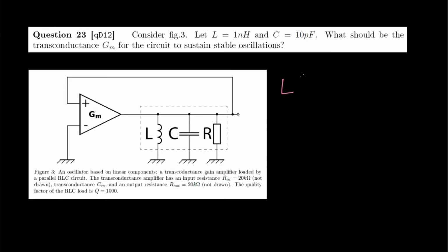So, to write that down mathematically, the Barkhausen criterion tells us that the open loop gain has to be 1 with a phase shift of 0. Since the phase shift of the open loop gain has to be 0, we know at least that the frequency of oscillation can be found when the impedance of this RLC circuit has no imaginary component. In other words, the impedance of this capacitor and this inductor completely counteract each other and can therefore be cancelled in this drawing. We can now look at the open loop voltage gain of the circuit.